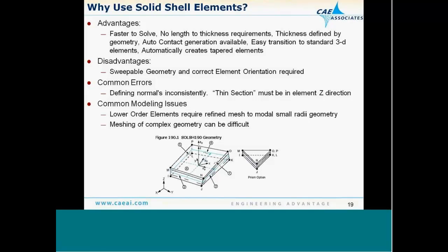You want to make sure that you mesh with the thin surface operation, or if you're defining them manually, you create a consistent z direction, since the thin direction, where ANSYS will decouple the translational response and the moment response, is only defined correctly if the z element coordinate system is normal to my solid shell elements.